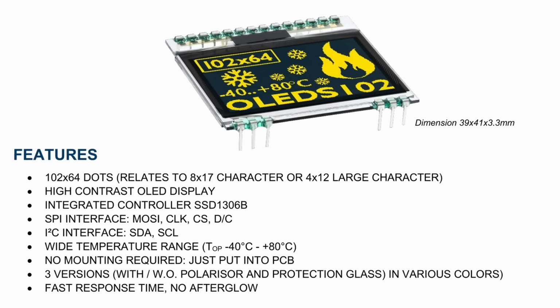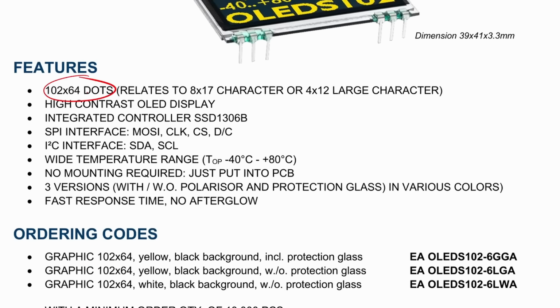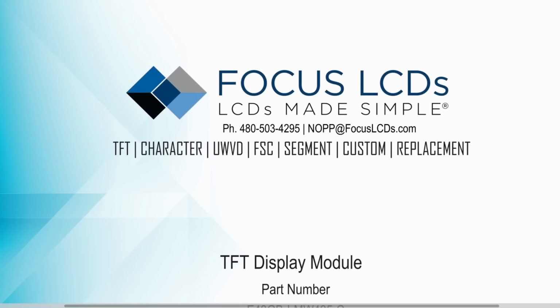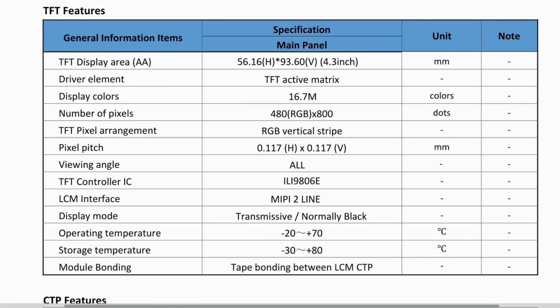The driver chip in each display determines which of these interfaces you can use. Smaller displays, or displays with limited color depth, can get away with I2C or SPI and still refresh at a reasonable rate. If you pick a high-resolution display with 24-bit color, though, then you'll likely need a faster interface like MIPI-DSI. Make sure you consult the datasheet when buying a display to see what you're getting yourself into.